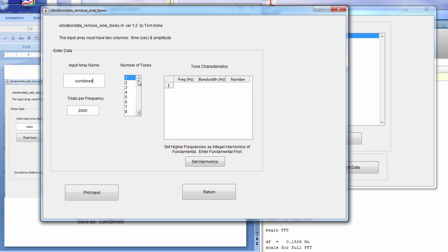We already have done our FFT and our PSD, and obviously from our synthesis, we know that we have a spectral peak at 100 hertz. The bandwidth allows for a little variation. You take the bandwidth and take 1/2 of it, and that's a plus and minus about this nominal frequency.